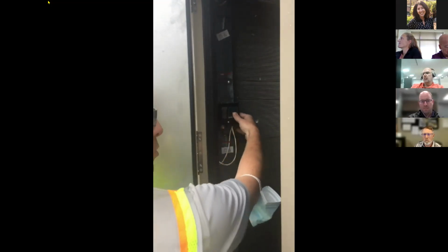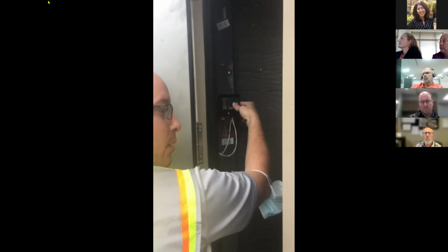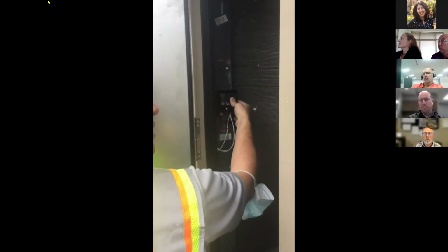Okay, so one way we can test the safety, if you don't have canned air on you, or for some reason you can't get that to work, whatever your dilemma is, you can do the hold the button test. So I'm just going to do that here. We just hold the button in at the FreeStat panel here, for a few seconds, and we should be able to hear the unit shut down.